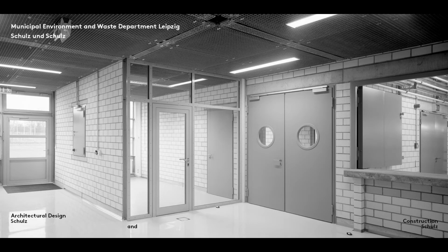All the dimensions in a masonry construction are based on the principle of combined modular dimensions, joints, and working sizes. This principle of modular coordination is particularly important when masonry is to be left exposed for design reasons. Where this is the case, other components such as window lintels, window breasts, supports, etc. must also follow the rules of modular coordination.